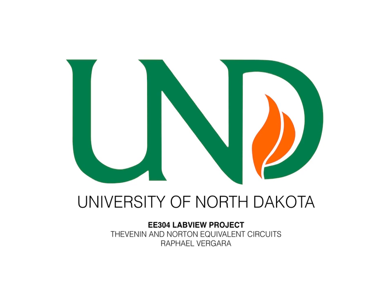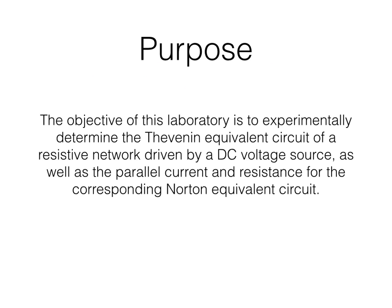Welcome to my concept of Thevenin and Norton Equivalent circuits using myDAQ and LabView. The objective of this laboratory is to experimentally determine the Thevenin equivalent circuit of a resistive network driven by a DC voltage source, as well as the parallel current and resistance for the corresponding Norton equivalent circuit.